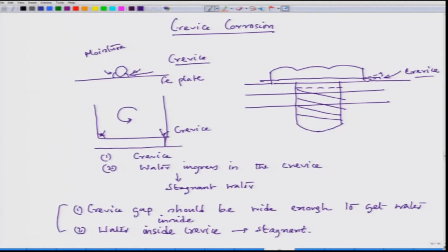So, if this is the thickness of the wall, at times the wall can be punctured and there could be leakage. This is the level of crevice corrosion that is possible. Here also there could be crevice corrosion around this region. The corrosion would be so fast that even without giving any signature, it might leak the container.